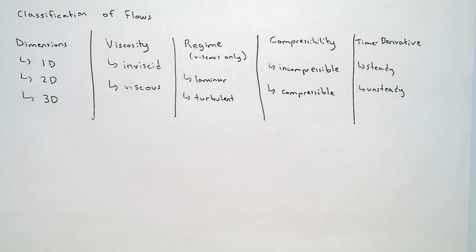Now this obviously is a simplification, but it is a simplification that allows us to calculate flows a lot faster. Steady flows are usually, not always, but usually modeled in industry as one-dimensional. Here we may look at steady flows that are two-dimensional or even three-dimensional because here we have math. We can do whatever we want with that math. But in industry, you'll see that most flows that are modeled as steady are for the most part one-dimensional.